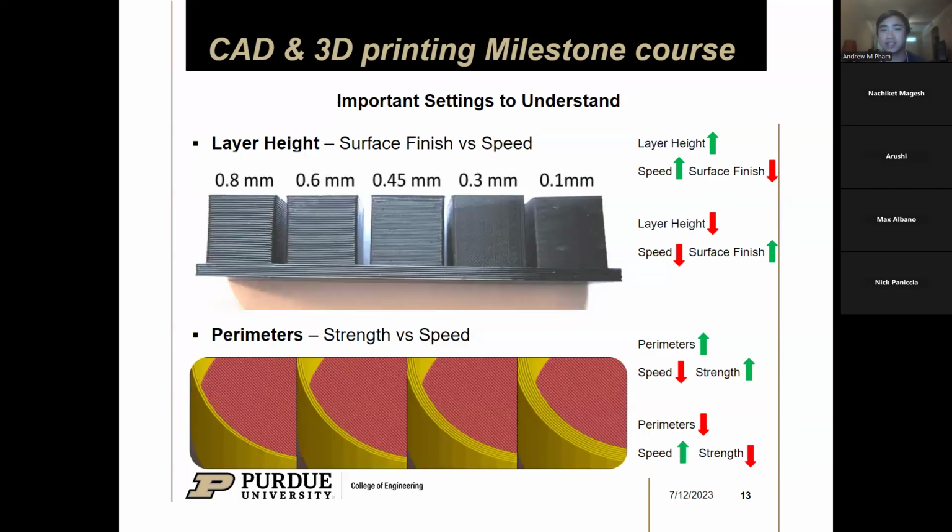One of the advantages of a really fine layer height is that you get a high level of detail, right? The layer lines are less noticeable, and if you have really small features, at least on the vertical axis, they will come out better. But it comes at the sacrifice of speed, and sometimes at the sacrifice of strength, but that's usually somewhat marginal, depending on what you're doing.